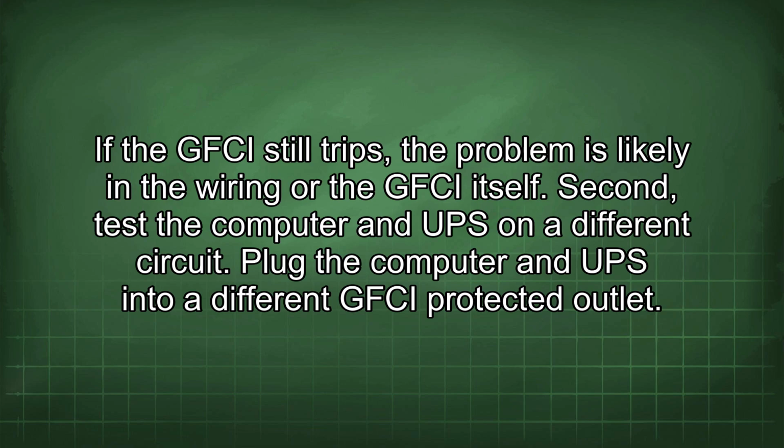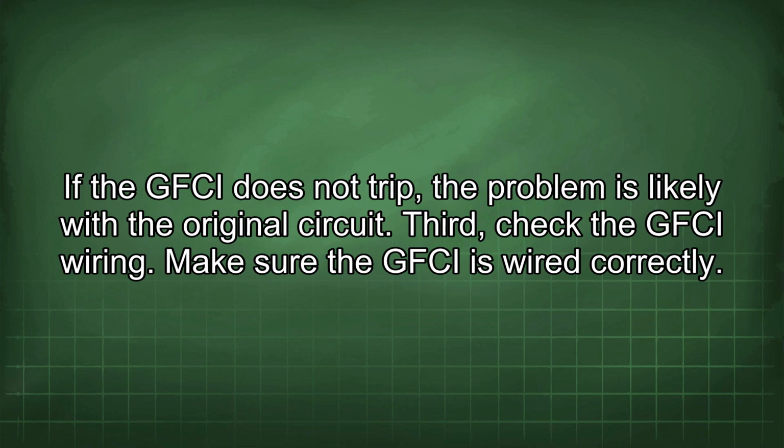Second, test the computer and UPS on a different circuit. Plug the computer and UPS into a different GFCI protected outlet. If the GFCI does not trip, the problem is likely with the original circuit.